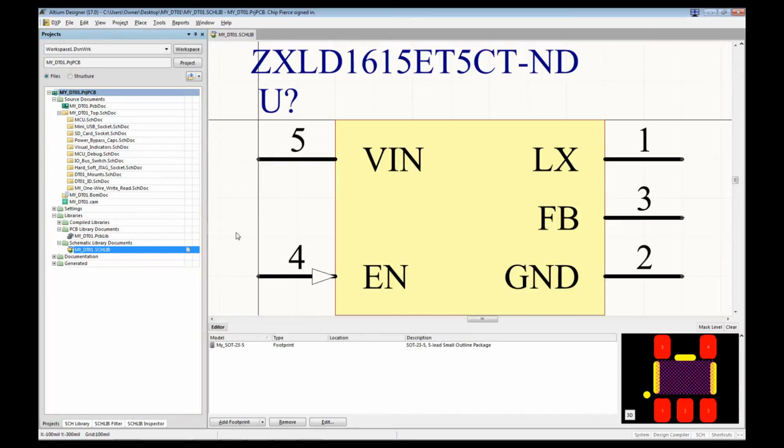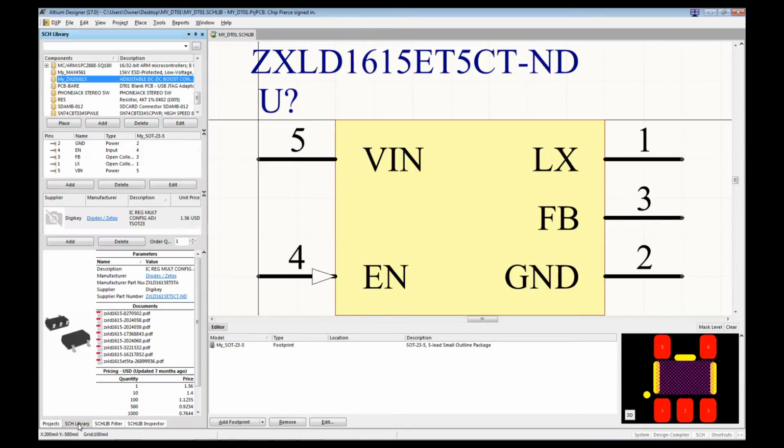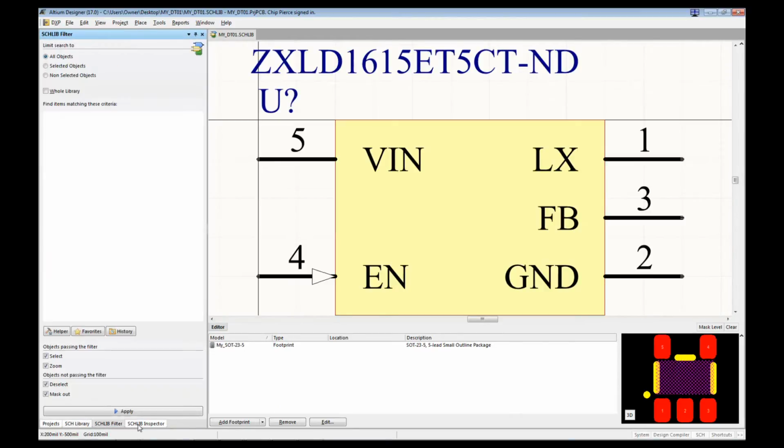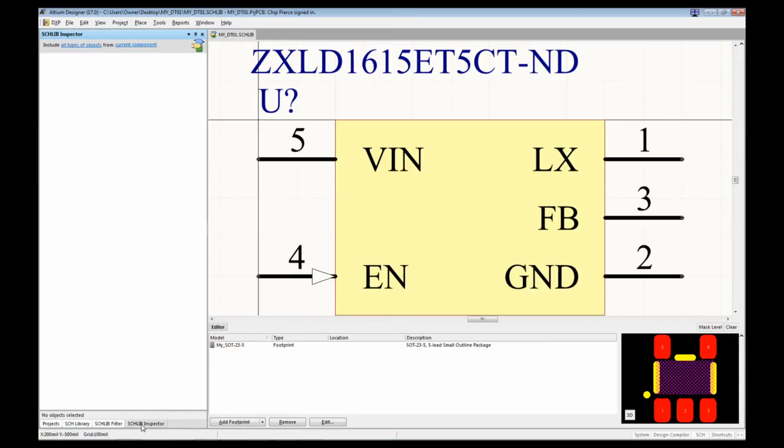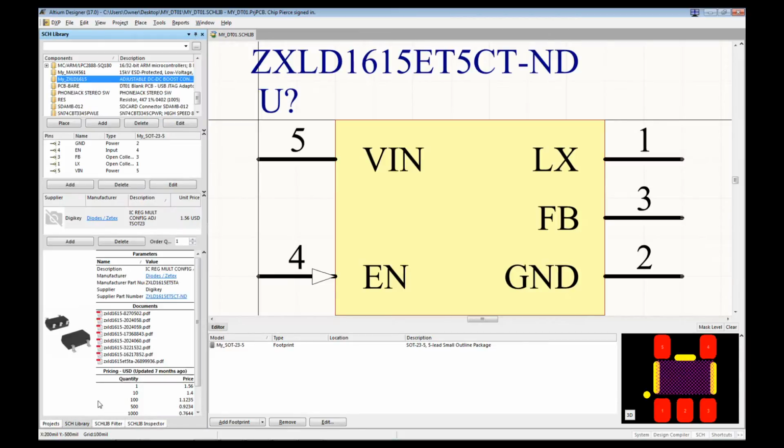First, students will open an existing schematic library and experiment with the 4 different workspace panels that are available. Down here on the status bar on the lower right, you click on the SCH panel button, and here are the 4 different workspace panels that are available and that I've got docked over here on the left.